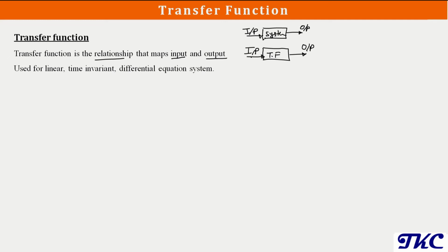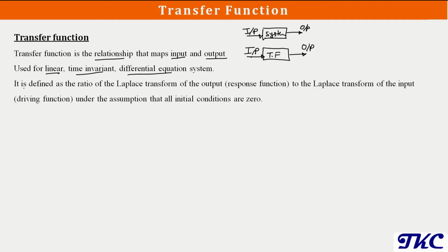So now, the transfer function we can use for a linear, time invariant, differential equation system. Now let's define the transfer function. We can define the transfer function as the ratio of the Laplace transform of the output of the system, that is the response function, to the Laplace transform of the input of the system, that is the driving function, under the assumption that all initial conditions are zero.